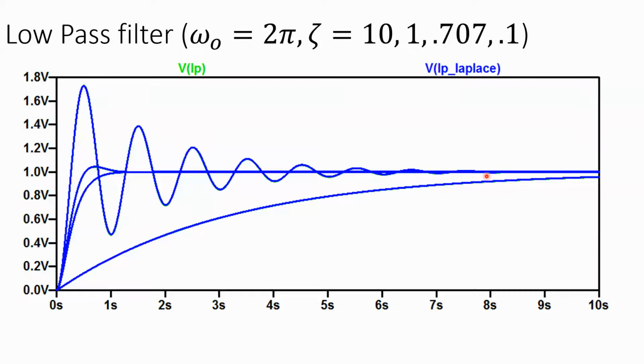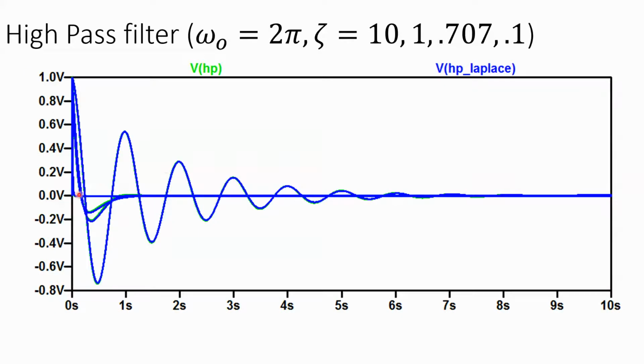What about high pass? Again, it's pretty good. Here we start to see some issues, but it's not really a problem. By the time you actually made this filter with component tolerances, that could swamp out any differences that you see to some theoretical calculation.